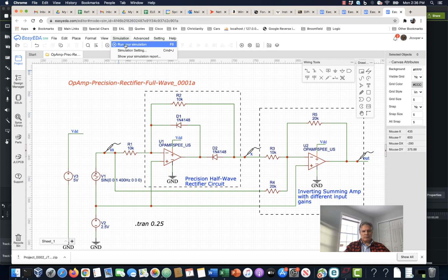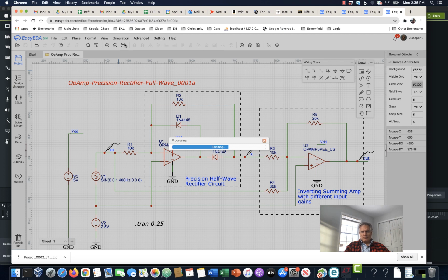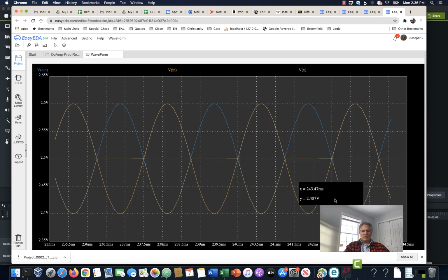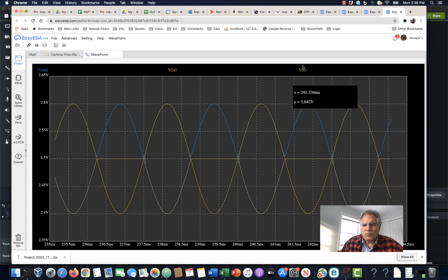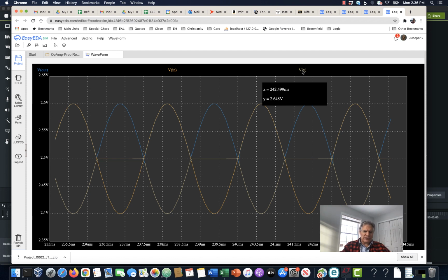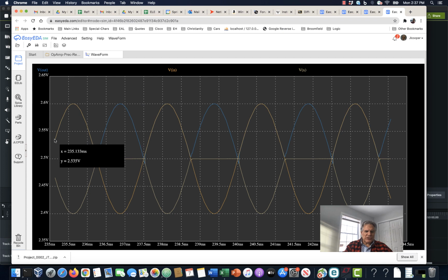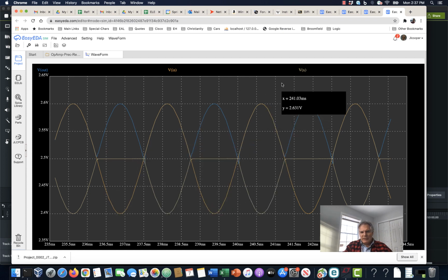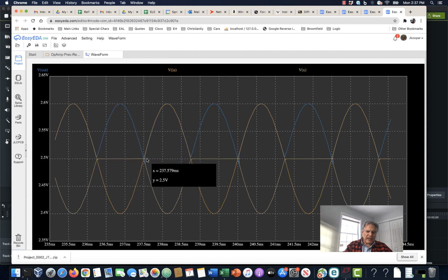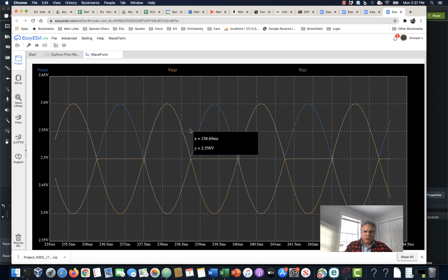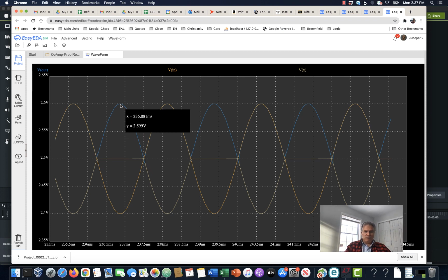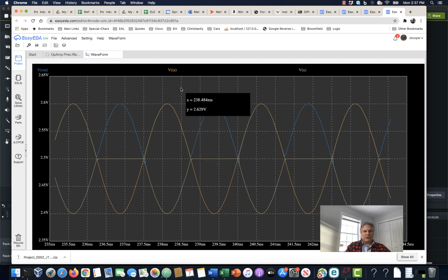And when we do this, if we look at our simulation, I'll zoom in on just a few cycles here. You can forget the tan signal here, Vx. That's the signal in between the two, but the input signal is this sine wave, this bronze orangey thing, and it's a true sine wave. The output waveform looks like a half wave here, but it's also behind the input waveform. So it's a full wave rectified sine wave, and again, it's only 0.1 volts peak. So it's getting around the diode drops and giving us the signal that we want.